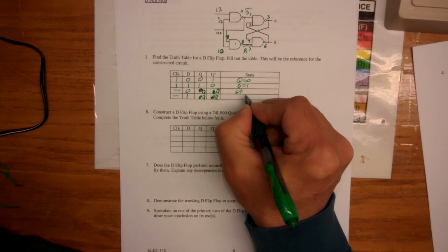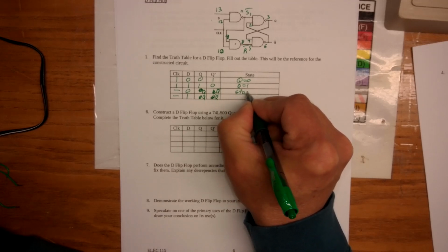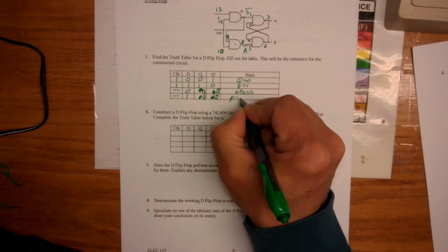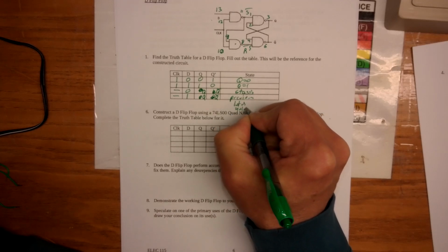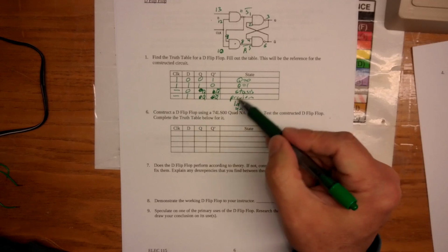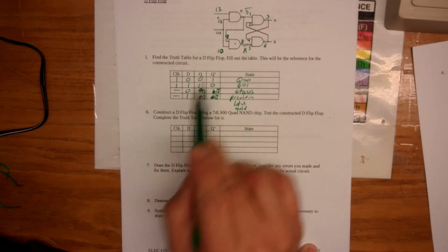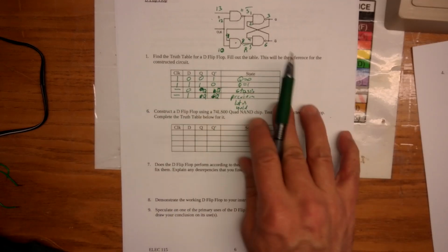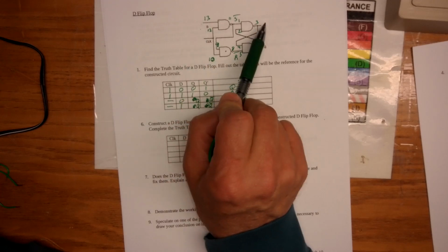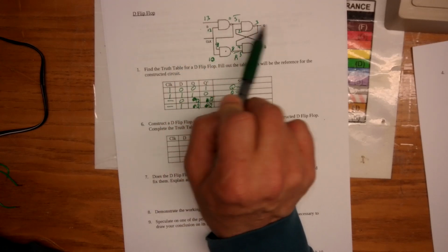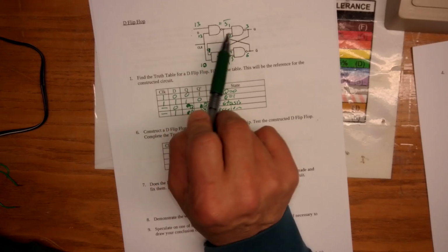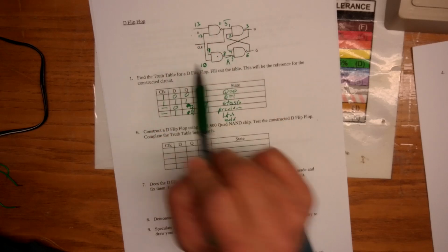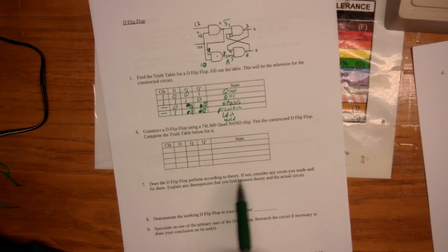You can call it stasis, you can call it previous, you can call it latch, you can call it hold. My concern here is most of you understand it doesn't change. The clock's not going. So you should build this. This is not real exciting because you set D. It'll be exciting it's working, but if D is 1, that's 1. If it's 0, it's 0. Run this at 1 hertz and you should be able to see a little delay when it changes waiting for the clock. Fill this out. Should work according to theory.